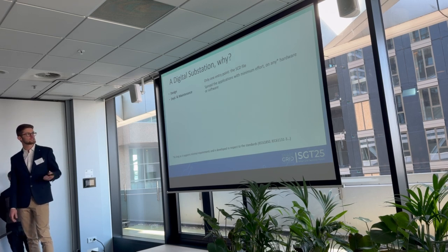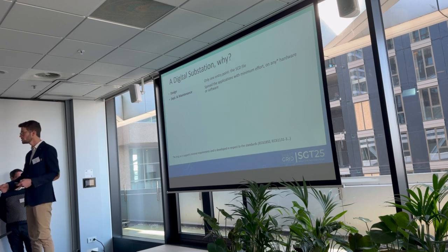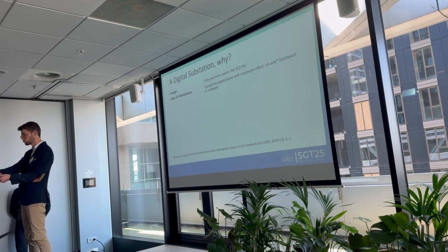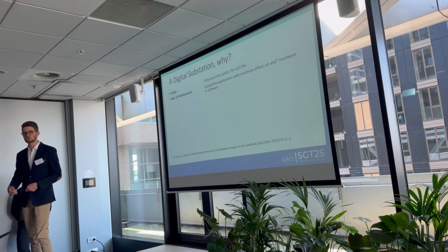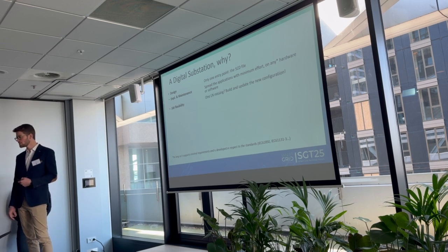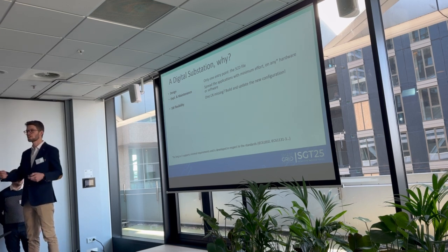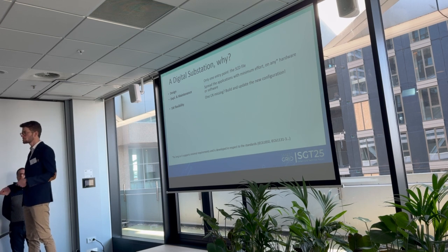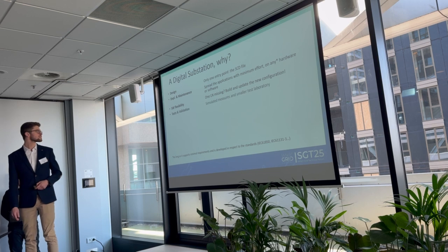Then deployment and maintenance, because if it's digitalized, theoretically you can deploy it easily. You don't have to go on site. You just have to have a distant platform, and then you can deploy your images, your virtual IEDs, your protection, stuff like that. Also software flexibility, because if one logical node is missing, one IED is missing, you just have to replace an image. Finally, you just recreate the logic, add what's missing, and then you deploy the new image, validate it, test it, and that's it.